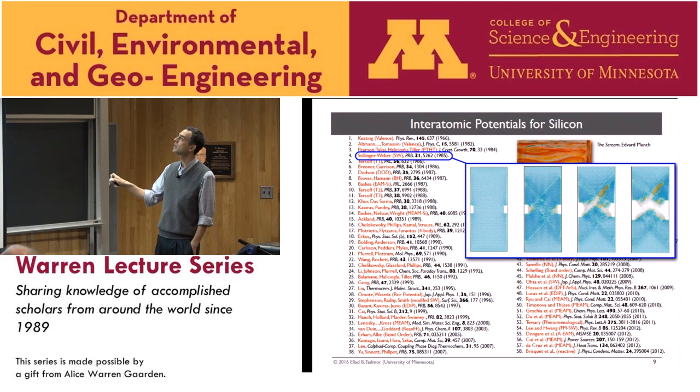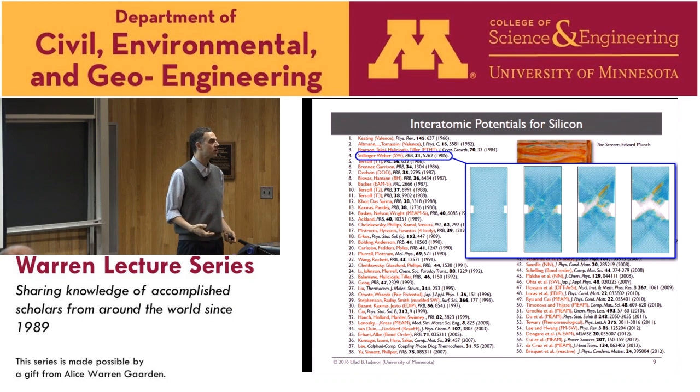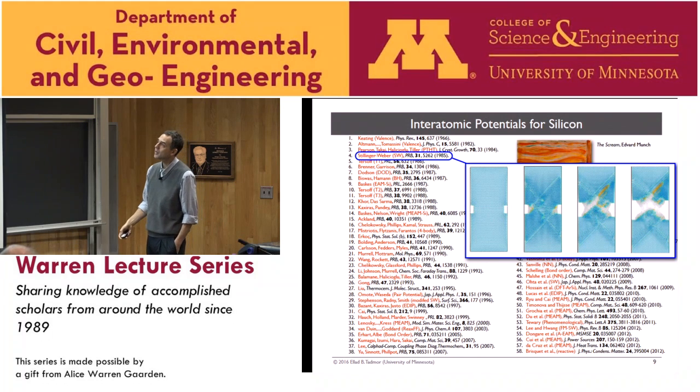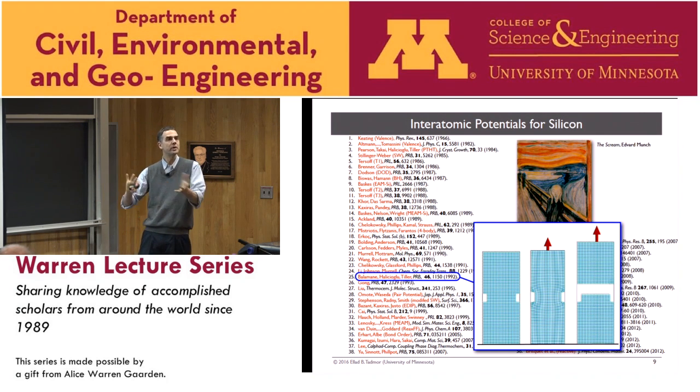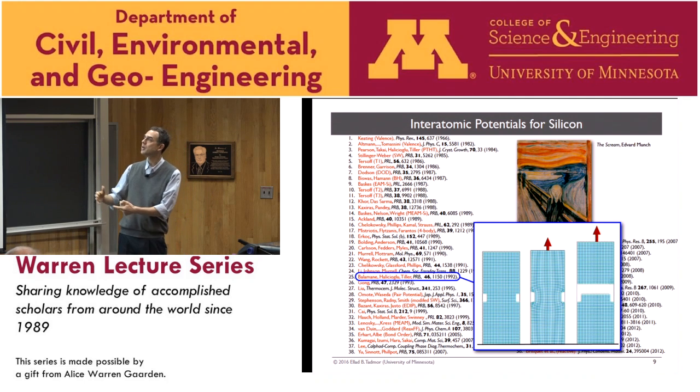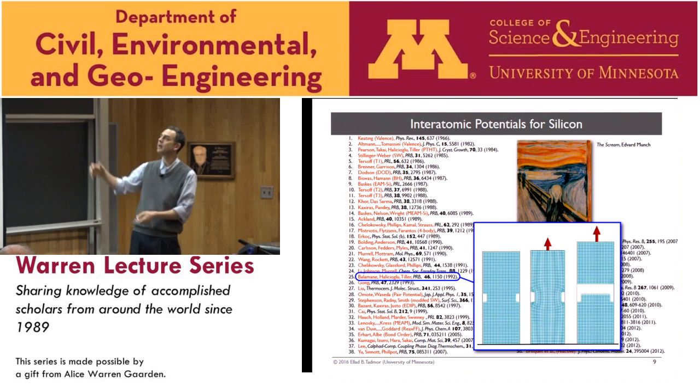So this is a double-edged notch of silicon. If you pull on it, you see these patterns here. These are dislocations that are being formed. And you just have a lot of plasticity. It's behaving like copper. It's not behaving like silicon. Right? Silicon is brittle. If you drop silicon, you get a lot of little pieces of silicon. This thing wouldn't. It would just bend. But if you take another one, this one does break in brittle fashion. And so each one predicts different things. And one of the things we're trying to do is get a handle on how do we evaluate these things.